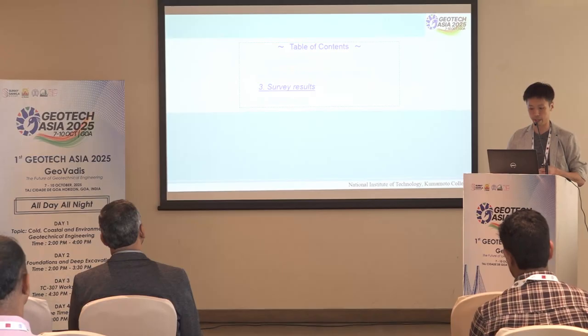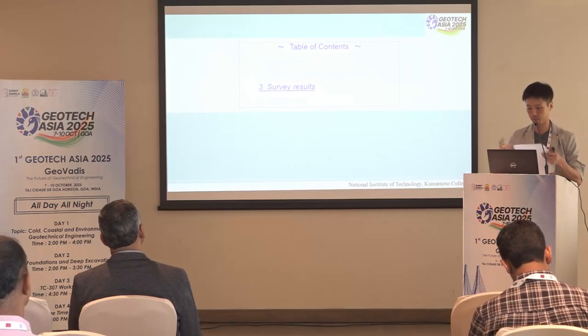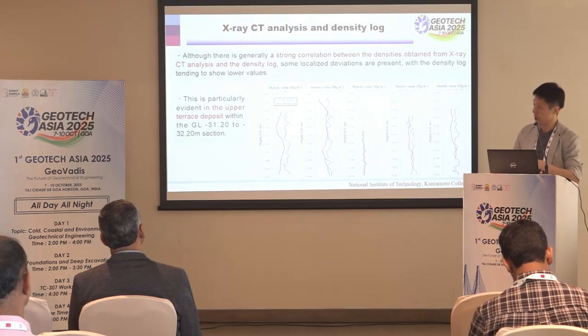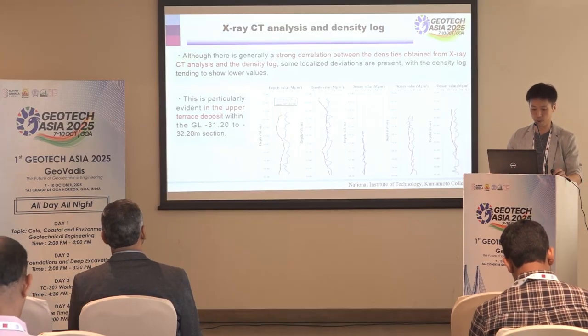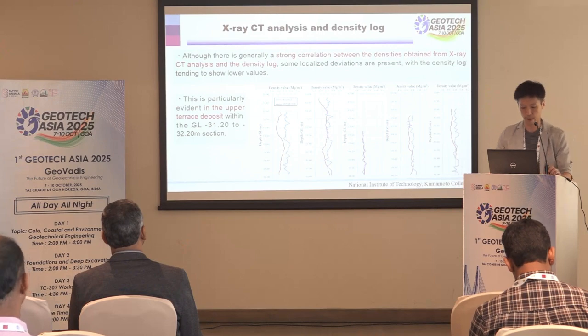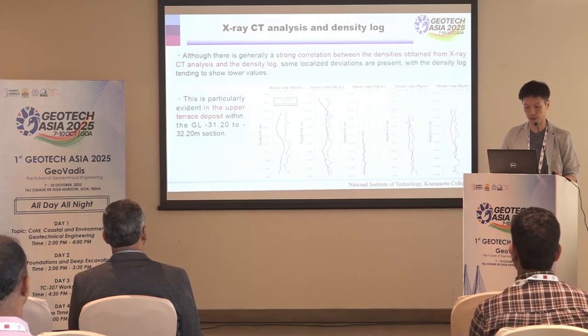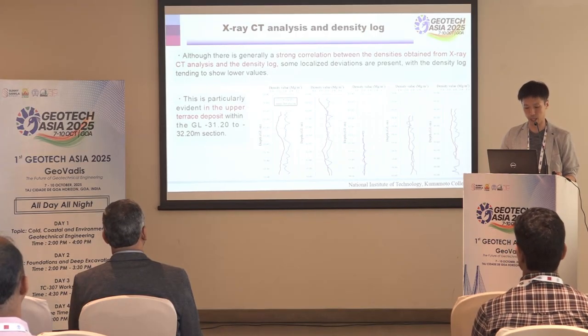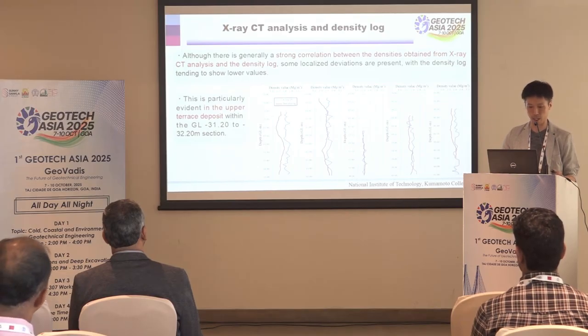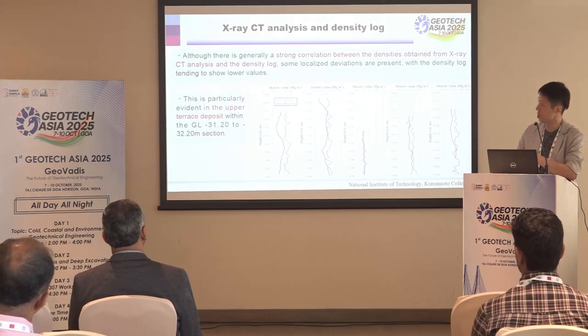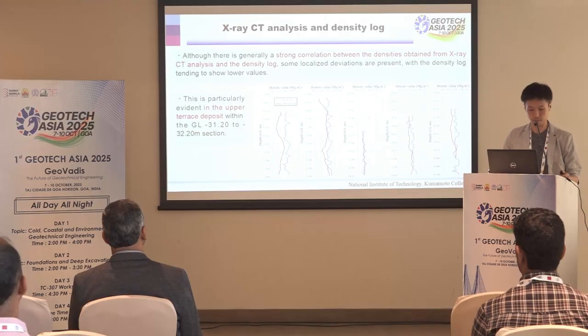Next, survey results. This figure shows the depth distribution of density values obtained from X-ray CT and the density log. The terrace deposit layer, which serves as the bearing stratum, has been identified from a depth of 30.82 meters from here. So these are the terrace deposit areas.